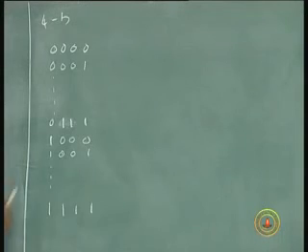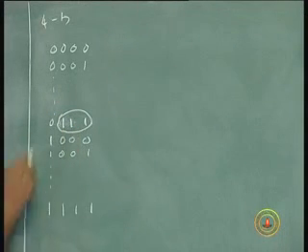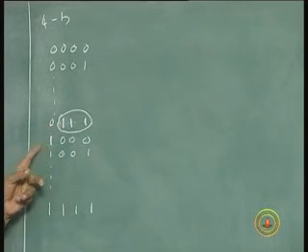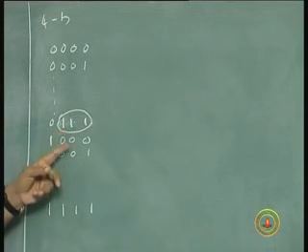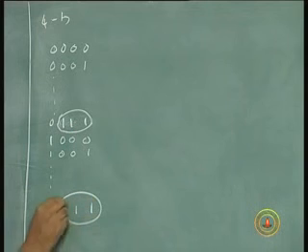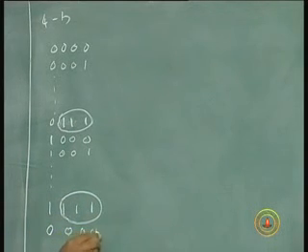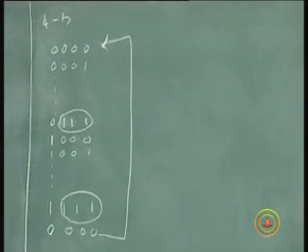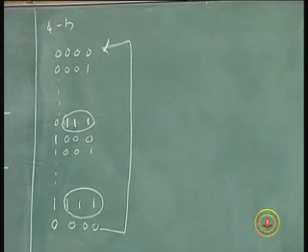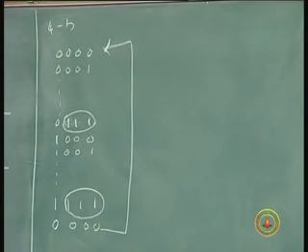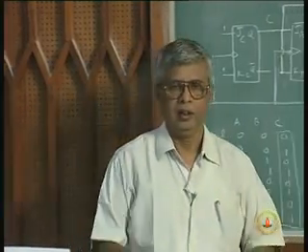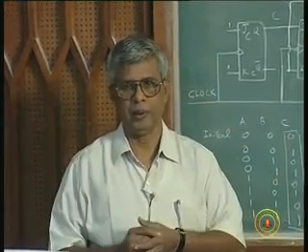Here these 3 becoming 1 1 1 will make the 4th flip-flop toggle and remain the same, because after that not all of them can become 1 at the same time. Again all of them will become 1 at the same time here, when it will become 0, which is the same as this. So I will repeat. When all the previous flip-flops have changed into 1, you want the toggling of the next flip-flop, and that has remained for several clock cycles before the next change can happen.